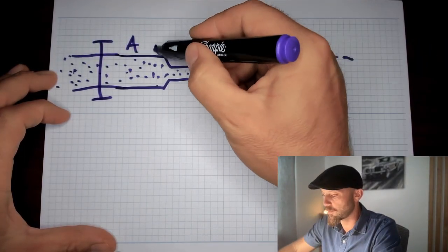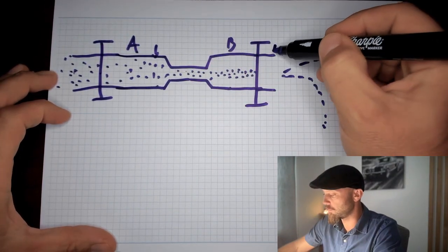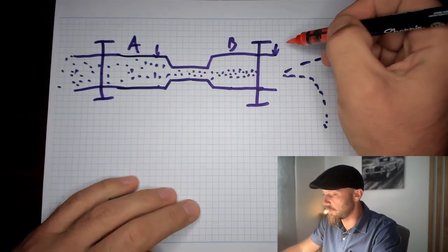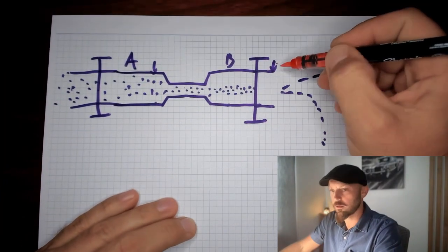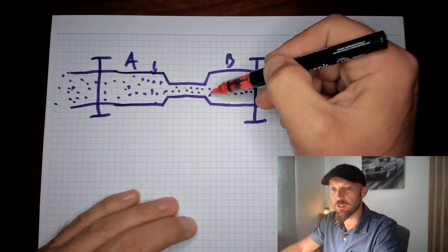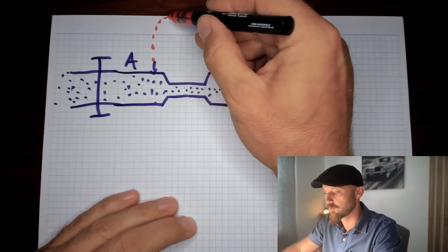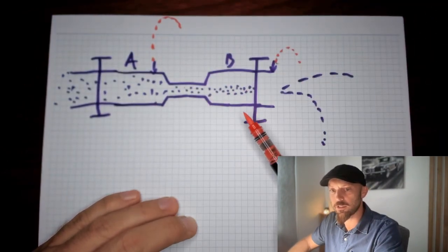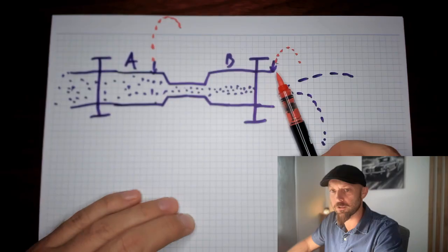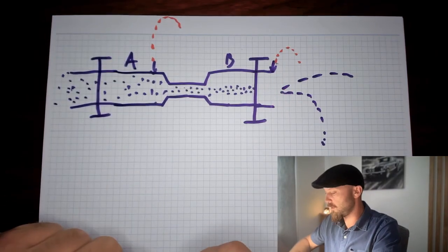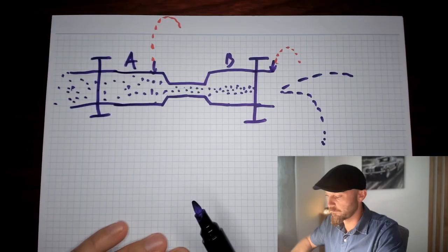However, if I would poke a hole here, or I would poke a hole here, the pressure would be different. This would only go up this much, whereas here, because it's before the kink, the pressure would shoot up all the way there. The flow of water is the same, however, the pressure between these 2 points is different. So now you can see what happened.